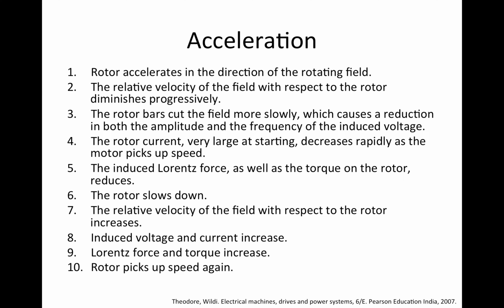It only depends upon the number of poles per phase, which is hardwired into the induction machine, and also the frequency of the three-phase alternating current, which is provided by the power lines. That's not going to change either. So the synchronous speed is not going to change.